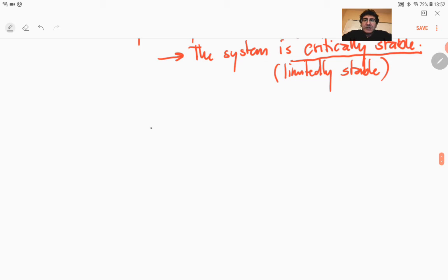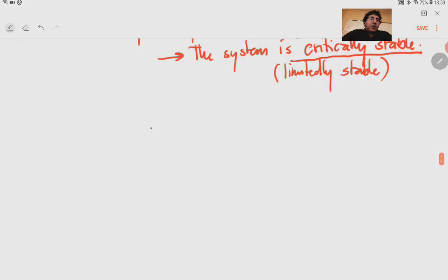But if you have a higher order system, you cannot talk about the exact behavior of the output or the exact behavior of the states without resorting to some kind of computer tools. Obviously you can use, for example, MATLAB's root finding function called roots in order to find all the poles of the system. Therefore, you can talk about its stability.